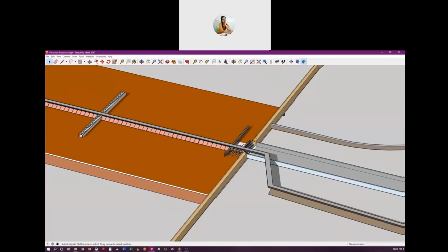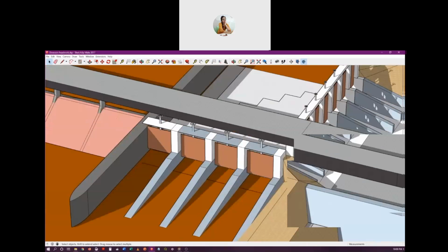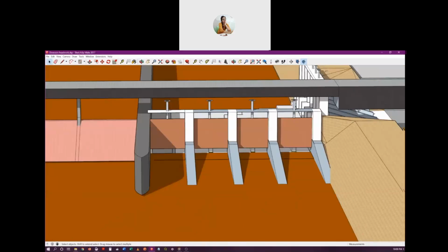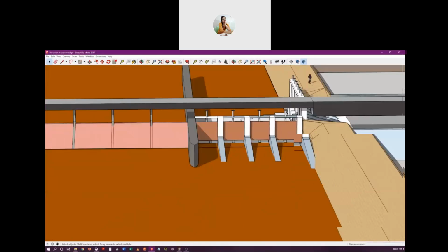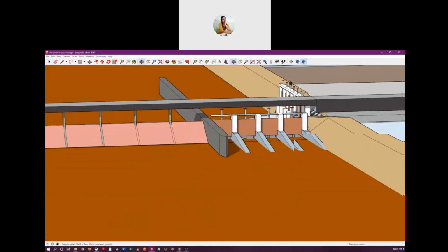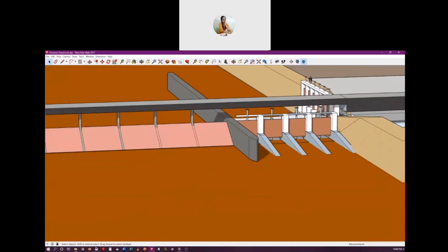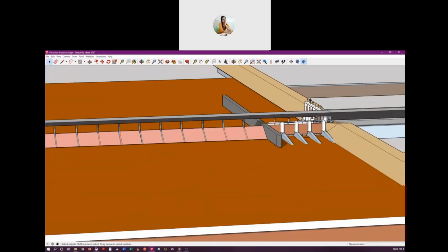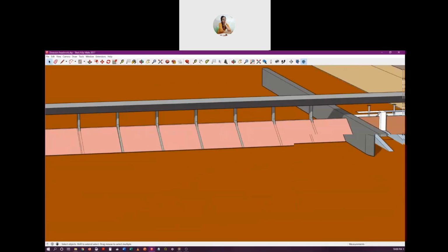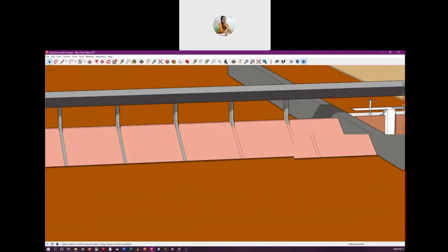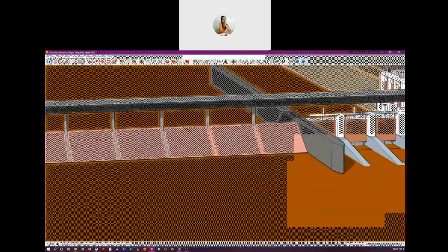And these undersluice gates, the number of these gates or the size of these gates will depend on the highest amount of flood that needs to be released when that flood comes. So here I've only shown 4 gates, but if the highest flood is of very large magnitude, then maybe we would have to provide some more gates here so that when flood comes, we have a larger discharge capacity so that the upstream is not flooded.